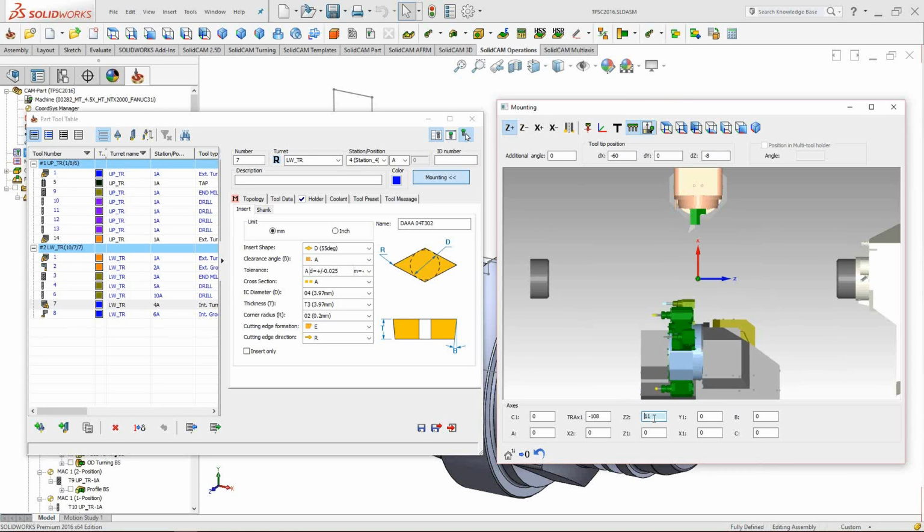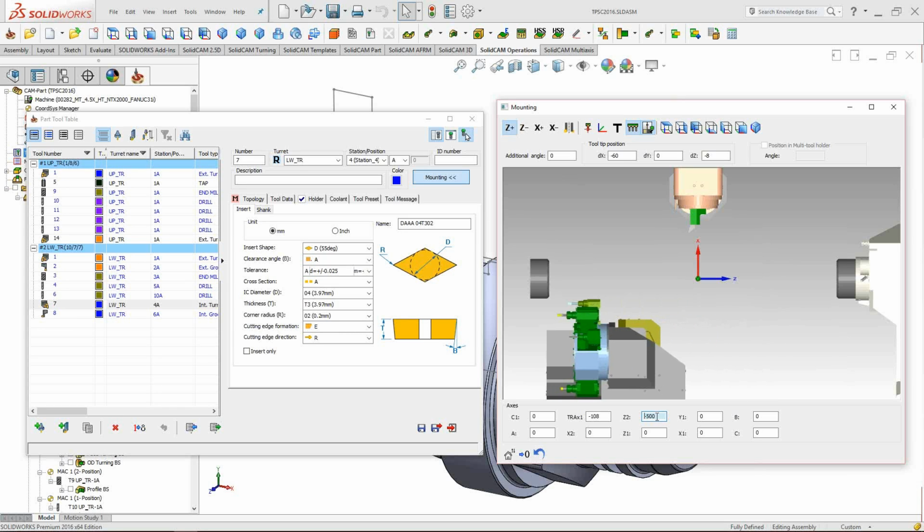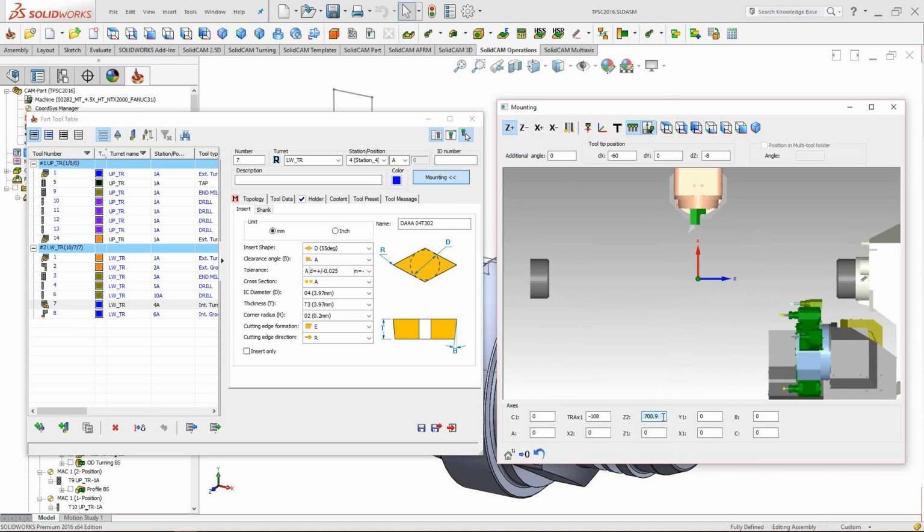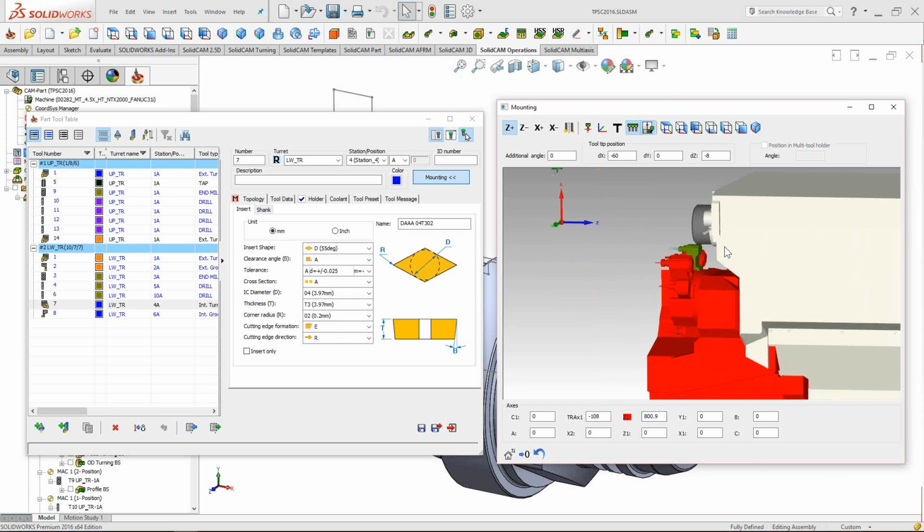Now you can use pretty much the standard feature that we already have in previous versions: scrolling with your mouse wheel will move your device by 1 millimeter. If you're holding the Control key, it will move with a delta of 100. And as well, we have here a very nice feature. If you're holding Control and Shift, it will shift it by 0.1. Of course, very nice feature, if you move your device out past the limit, the whole device will become red.